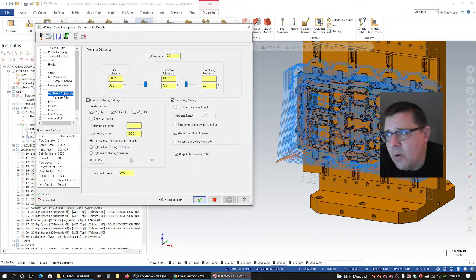When we're talking about tolerance, though, if I go to the arc filter tolerance, what we've got here, total tolerance, is really a combination of our cut tolerance and our arc line tolerance. So the cut tolerance here is a bilateral tolerance. It basically means from the surfaces of the model itself, the actual individual slices that the toolpath algorithm is taking are now allowed to go plus or minus, in this case 2.5 thou, from the nominal geometry.